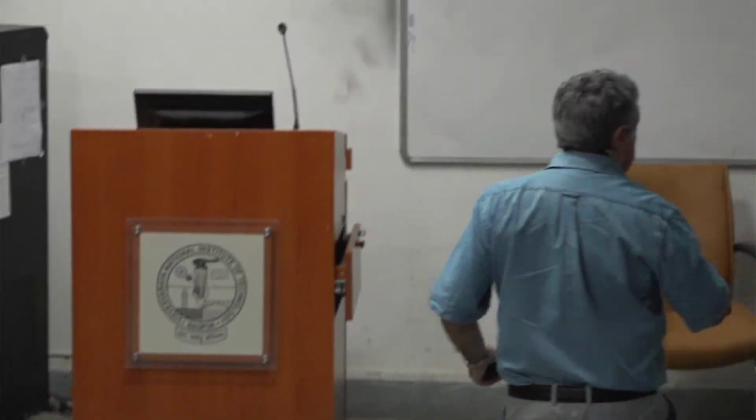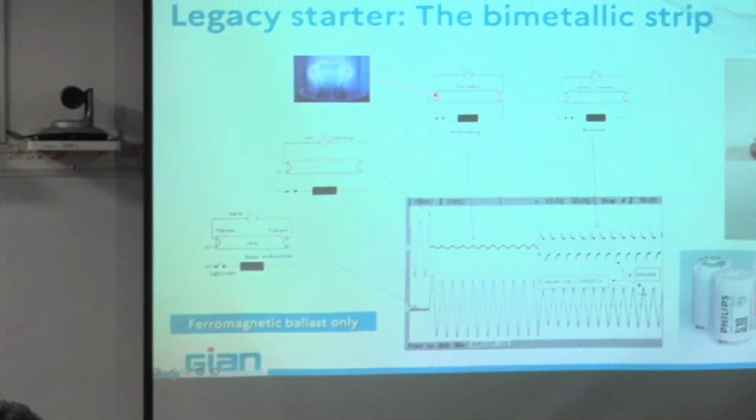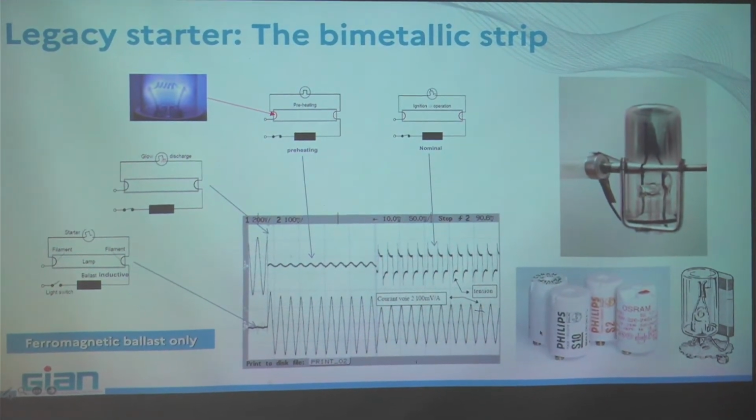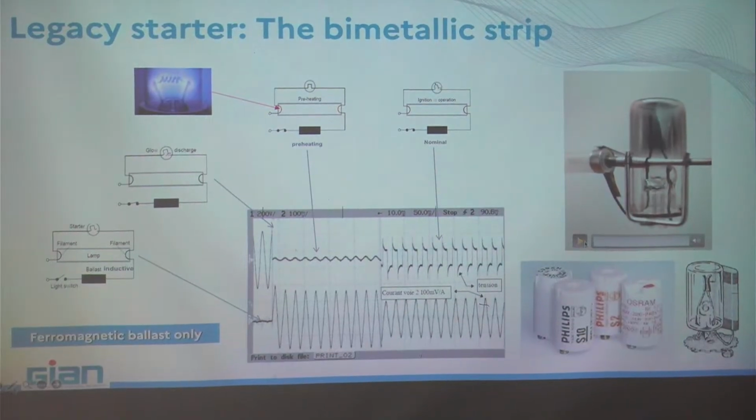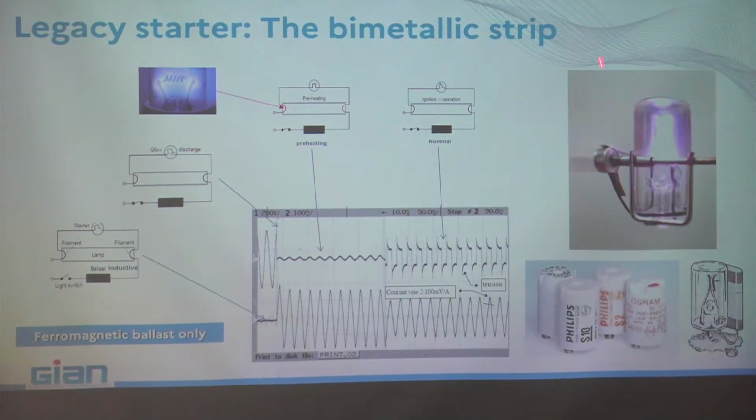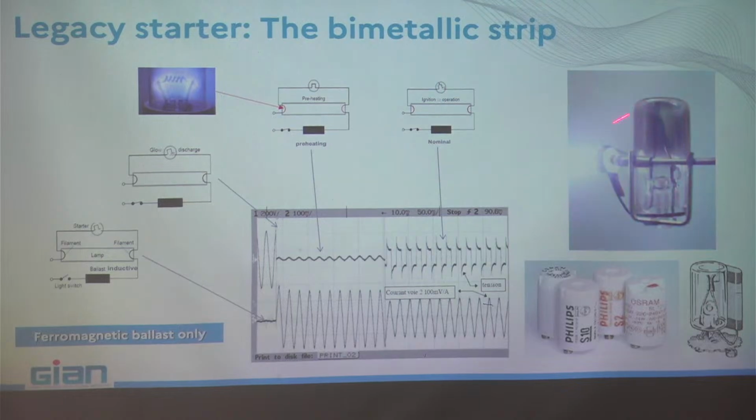Let's look here. I hope that the small video is working. Yeah, there it is. Look. The plasma appears, the lamp is here. It closes and opens, and then the lamp behind is ignited because the ballast here produced a more than 2000 volt impulse in a very short time, and this is enough to start the operation. I will show you again once.